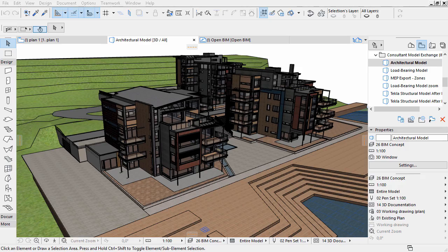In the following, we introduce the most important export and import settings. Architects must be able to cooperate effectively with the other disciplines throughout the design process. Graphisoft's Open BIM workflow supports IFC-based data exchange. IFC data exchange enables communication among different software programs used in design, construction, and facility management, provided that those softwares are certified for IFC. This way, designers and other consultants are not constrained to use a particular tool. They can work and communicate using their own software.